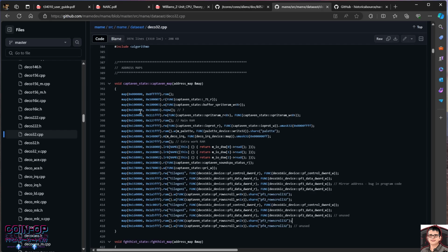Now, a lot of the time, these sorts of things, address generation and memory mapping, are usually done out of a custom chip or a GAL. Usually, for the boards that I deal with, I don't know back then in the 80s, they probably did it using regular logical components, as opposed to custom chips. But for the boards that I deal with, 96, 97% of the time, the actual game will use a custom chip to determine what these are.